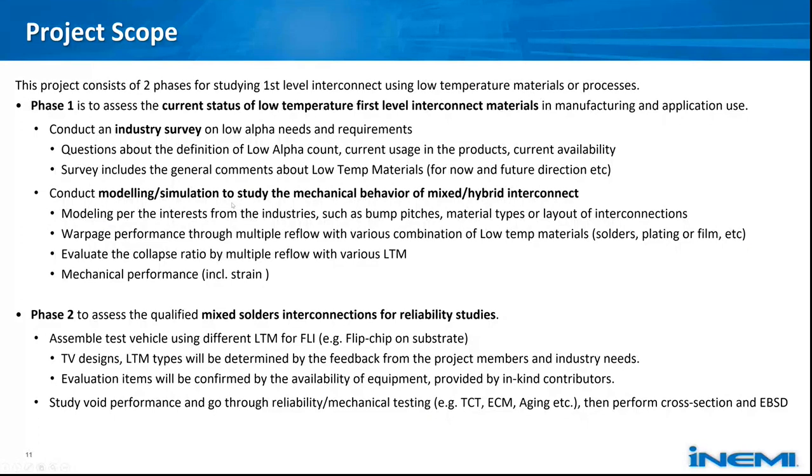And this simulation will focus on the warpage or the thermomechanical characterization through multiple reflows as a function of these low temp materials, and also evaluating different collapse ratios as a function of this reflow. And it will then characterize mechanical performance, for example, stress strain behavior, and maybe some electrical characterization as a function of low temp alloy properties.